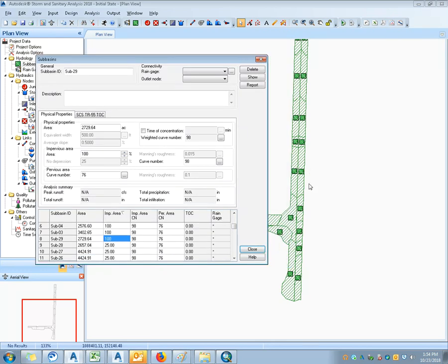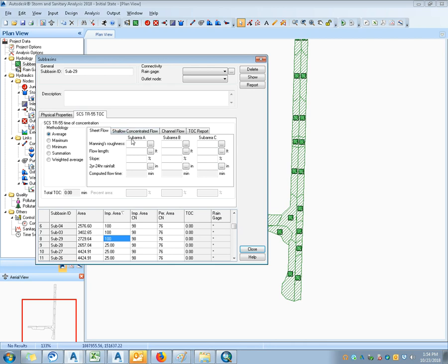This is all pretty straightforward because this is all a roadway right now. So we're going to have a time of concentration of 5 for pretty much all of this, and a curve number of 98. But when you're getting into bigger basin models, that's when you're actually having to calculate that information, and especially if you're changing these values, that's when I think you'd really notice a difference if there was some dynamic link in there.